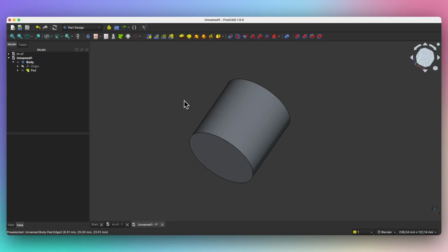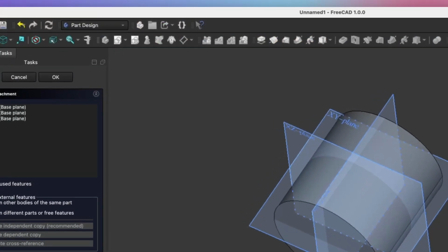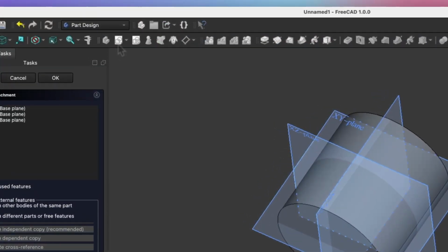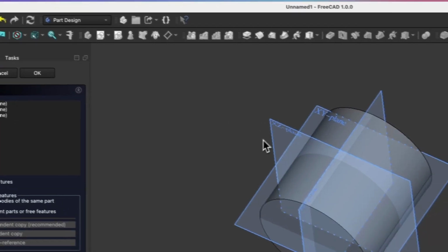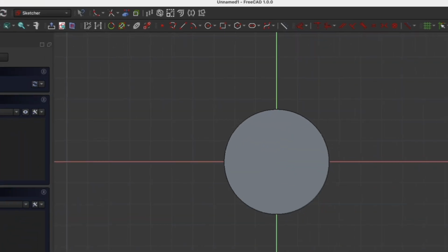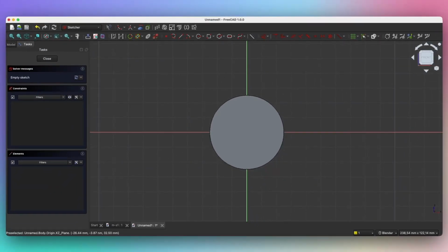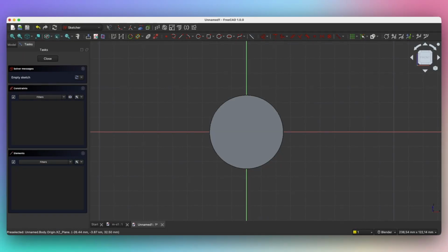This way we created the first fragment of the 3D solid, and now we will create another sketch. Select create sketch, and now as the sketch plane, let's choose the XZ plane, which we should have selected earlier, but in the meantime you learned how to change the sketch plane.